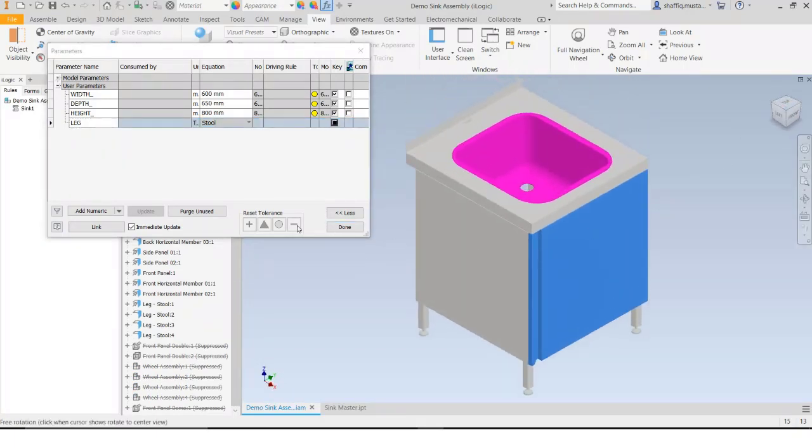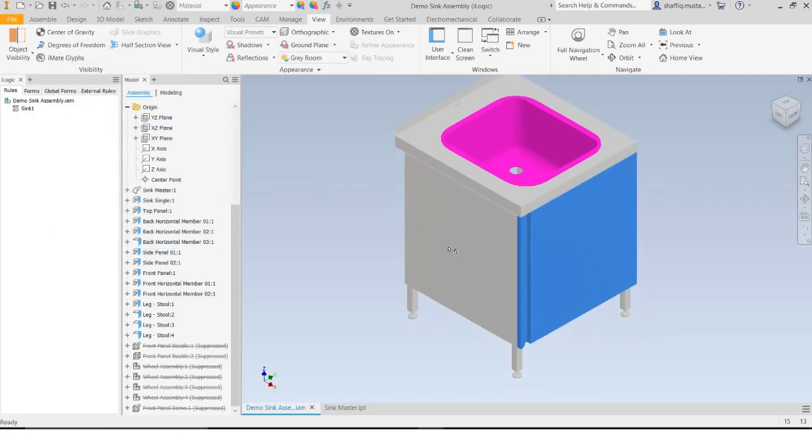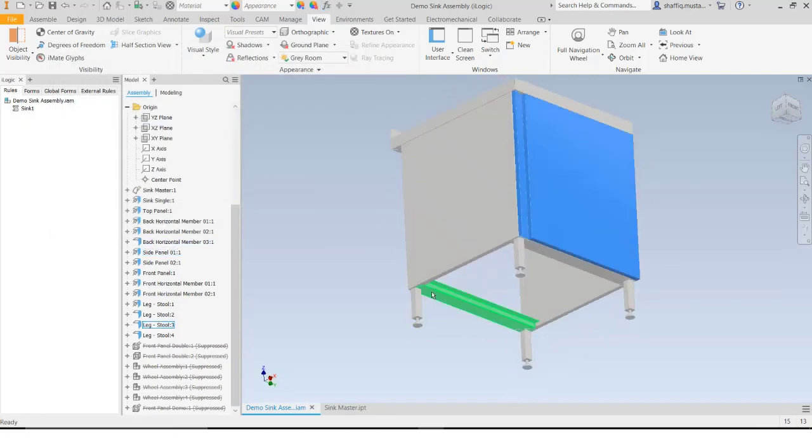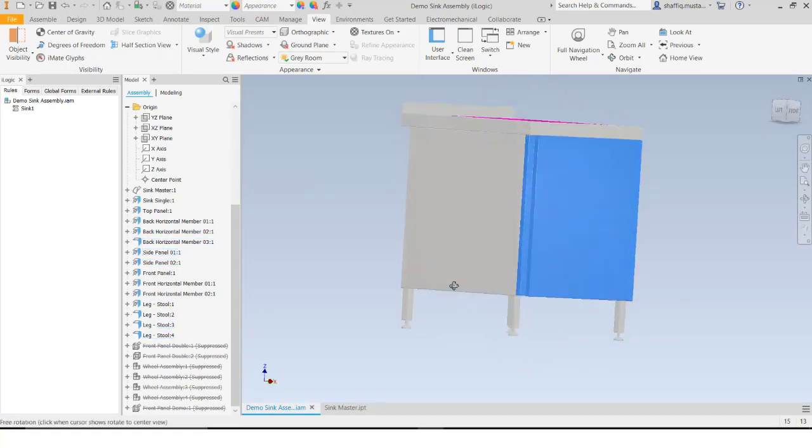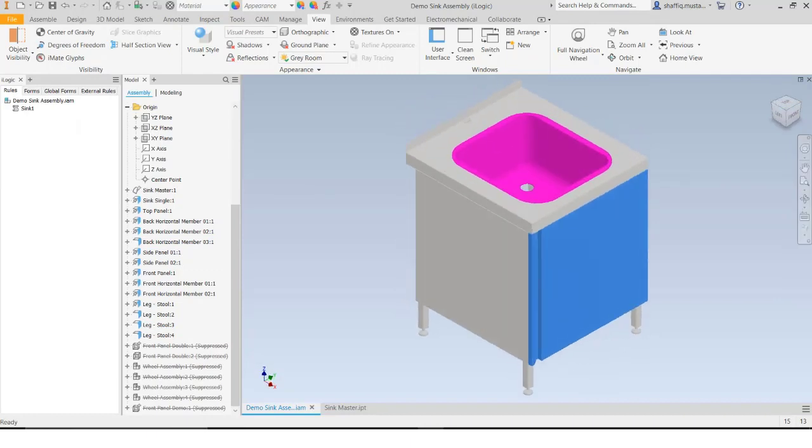So it really helps you guys in your design. You don't need to create multiple designs that have different sub-assemblies. As you can see here, I put both sub-assemblies here, but with iLogic I can select which one I want to show.